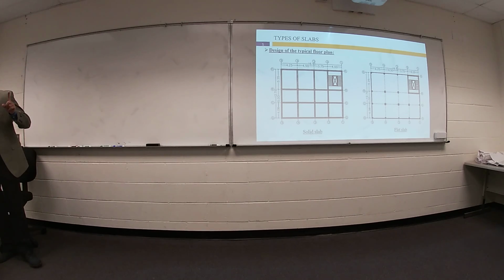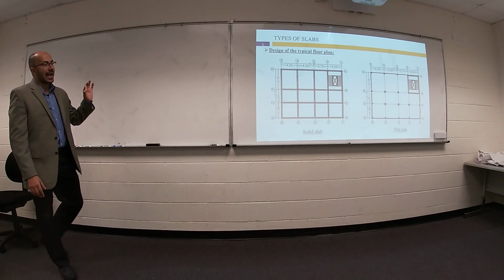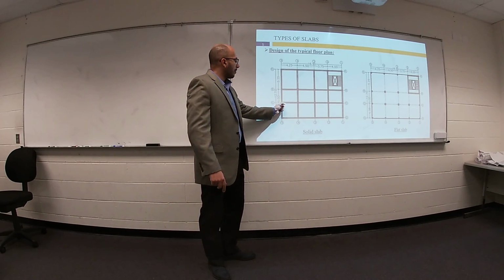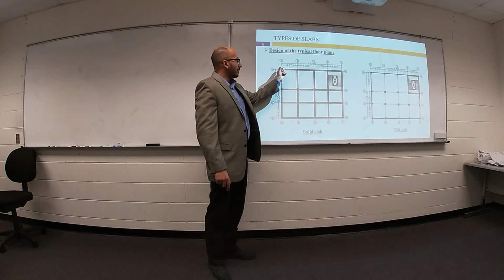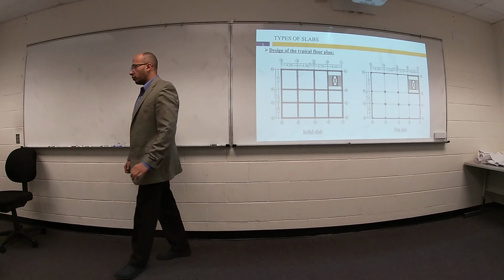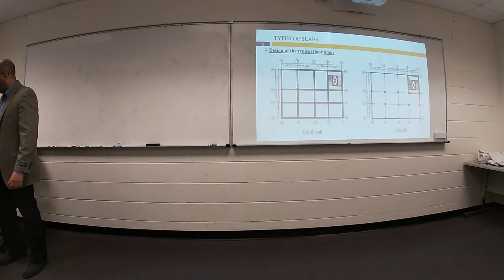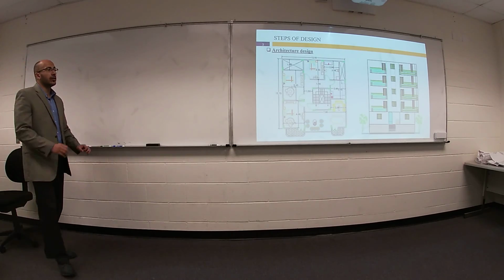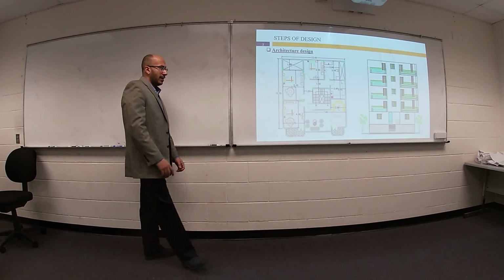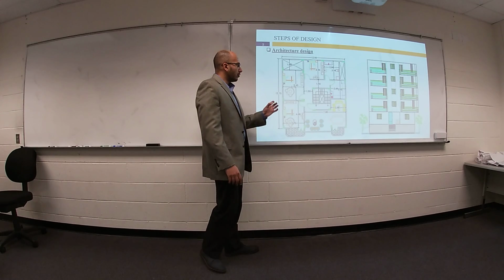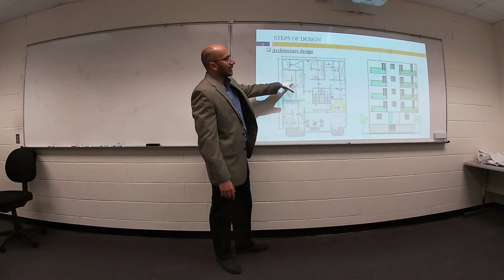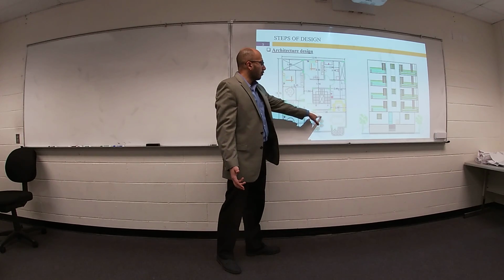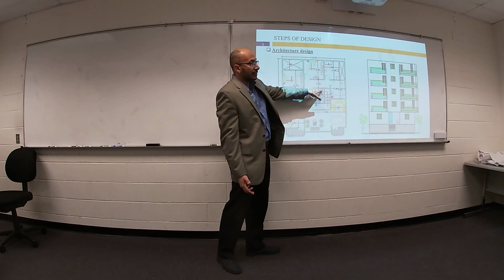One more piece of information. Where can I lay out or where can I put my column? The best scenario to arrange your columns is first to open your architectural plan. It does not make any sense to put your column in the intermediate area of a bedroom or living room or your stairs.